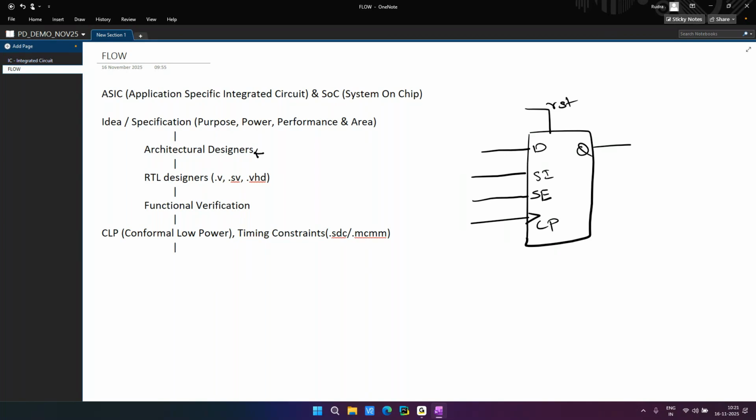So that means when I'm going for DFT, your SC pin will be equal to 1. First, there are two types of circuitry. One is like D, CP, Q, QN. Reset is optional, you can have it or not. So when we talk about a D flip flop itself, with reset, with SI and SC, without reset, only D pin related, like that we have different types of logic. Based on what is required, we will use only that circuit.